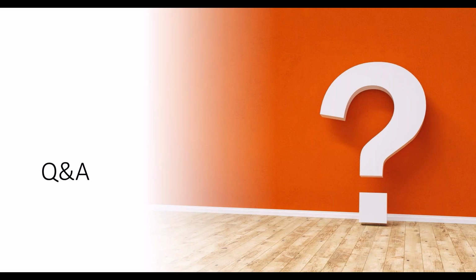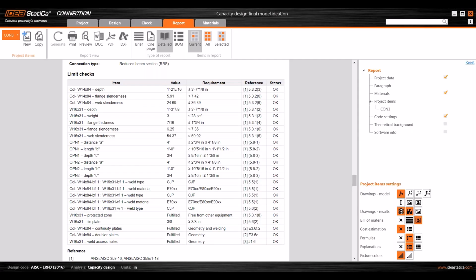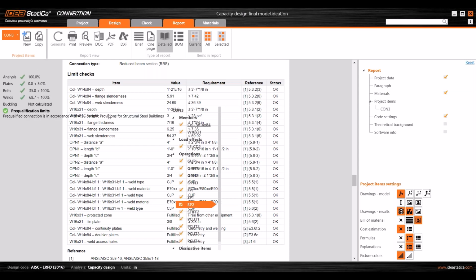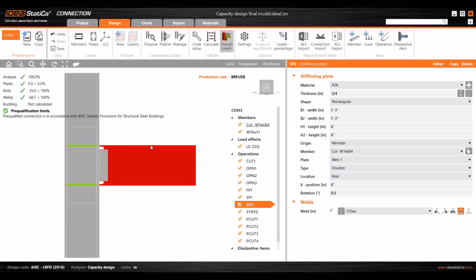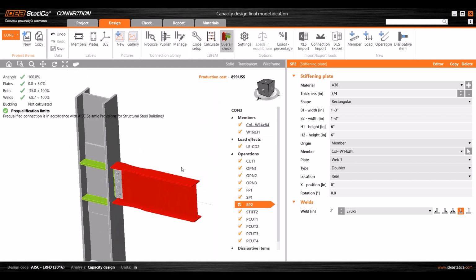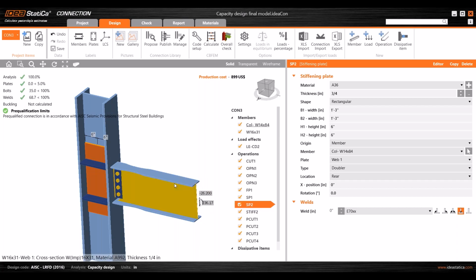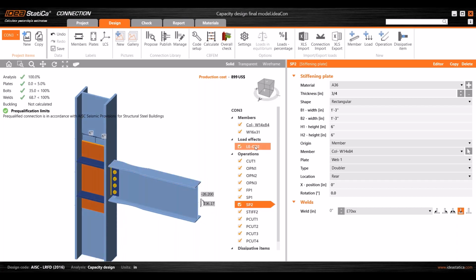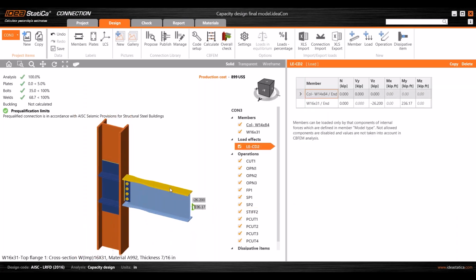Obviously, yes, you would want to include that in the design, but that would really be done initially in the stress strain analysis more so than the capacity design. The capacity design is meant to evaluate the dissipative item, which would typically be the beam. For the pre-qualified joints, the failure mechanism is supposed to be in the beam, the strong column, weak beam scenario. So I hope that answered that question.